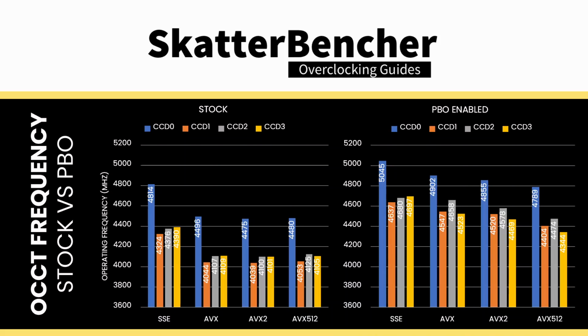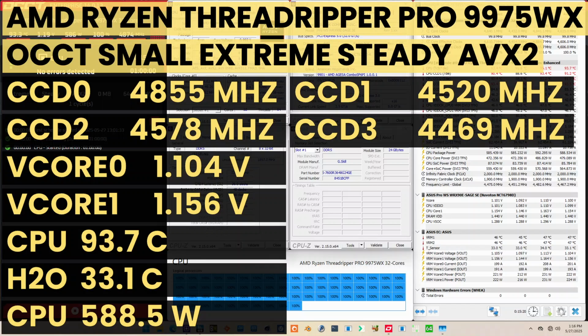Across the various OCCT workloads, SSE, AVX, AVX2, and AVX512, enabling PBO increases the operating frequency by up to 13.42% or 551 MHz. When running the OCCT CPU AVX2 stability test, the average CPU CCD0 effective clock is 4855 MHz, and CCD1 to 3 average effective clock is 4522 MHz with 1.13 volts. The average CPU temperature is 93.7 degrees Celsius. The average CPU package power is 588.5 watts.